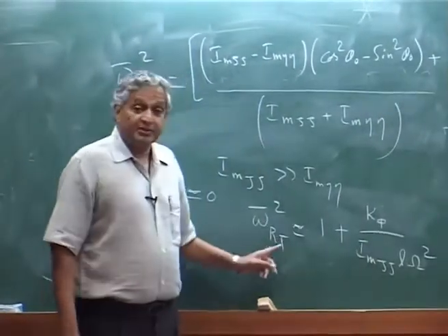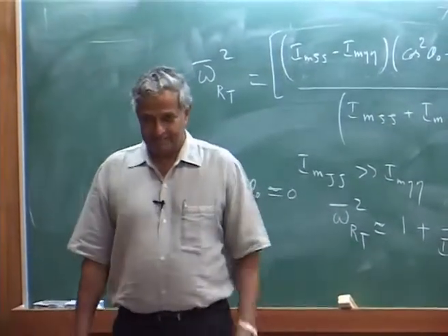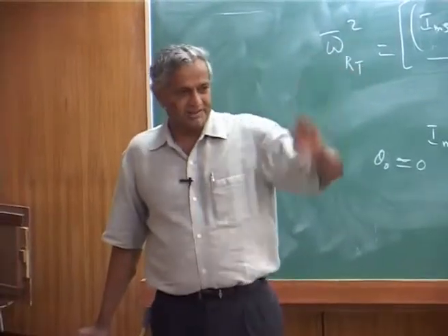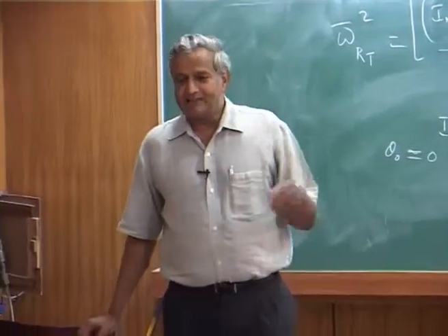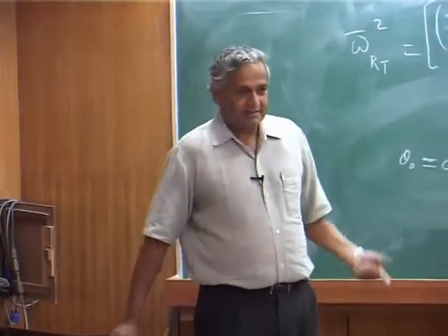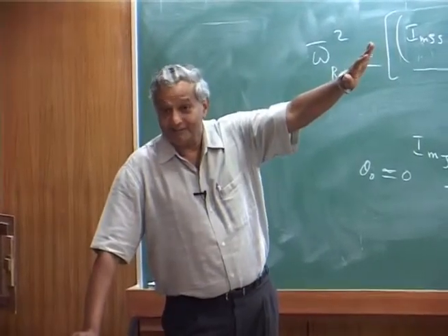Where do you place the frequency of the torsion? See, like flap is around 1.09, 1.04, 1.03, like that. Lead-lag is 0.25 or 0.7, non-dimensional. Torsion, you keep it far away.